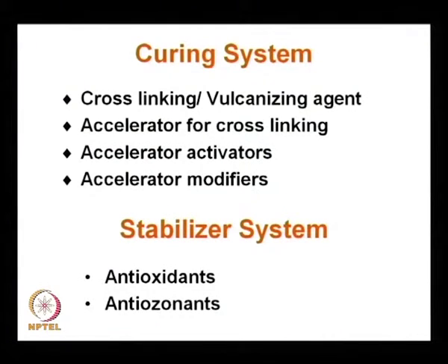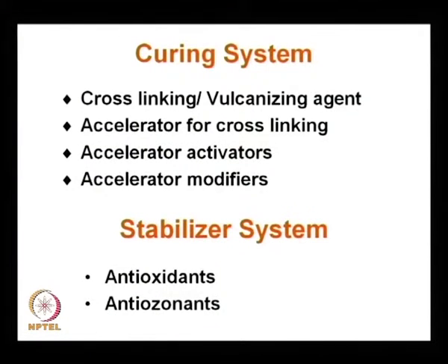Now, by using these accelerators and accelerator activators, these ingredients, it has been found that the vulcanization time has been reduced from 8 hours to 5 minutes or even 2 minutes. You see the influence or the role of accelerators, how important and essential it is in our products, you can understand from this phenomenon.